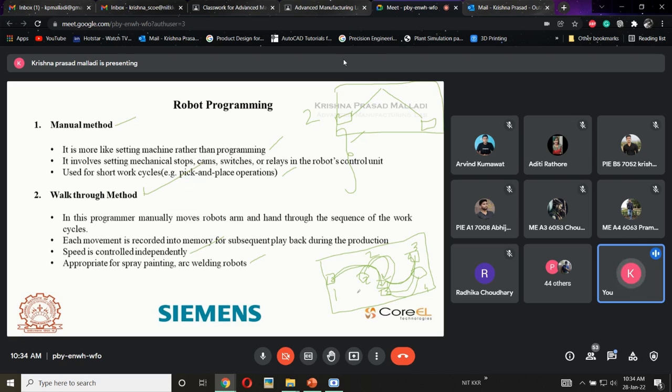Now what happened here, for each and every operation, the robot will store it in control memory. I mean, the robot will collect the data and record it on its own. So first operation saved, second operation saved, third operation saved and fourth operation saved. Here all these things you are running manually, so you will have the teach pendant with you and you are monitoring the program's behavior. If I run the cycle for 5 different repetitions, what will be the behavior?